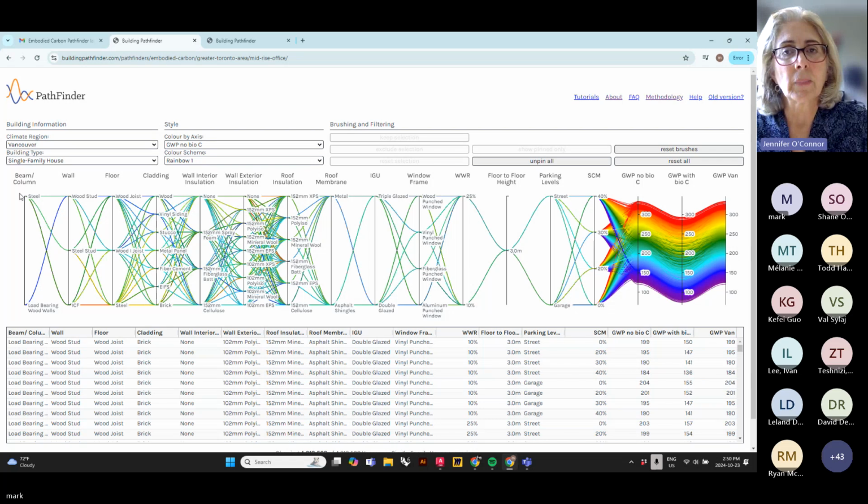Any other questions or comments? Yeah, I guess just on the SCM again: is it applied to all concrete elements evenly, verticals versus slabs and all that? Obviously you can load up on the vertical elements, not so much on the slabs, depending on the time of year that you're casting. So I guess it's just applied evenly, like 40% across the board. And the answer to that is yes.